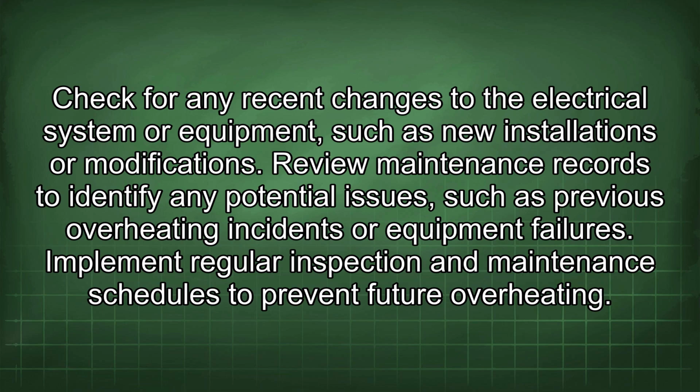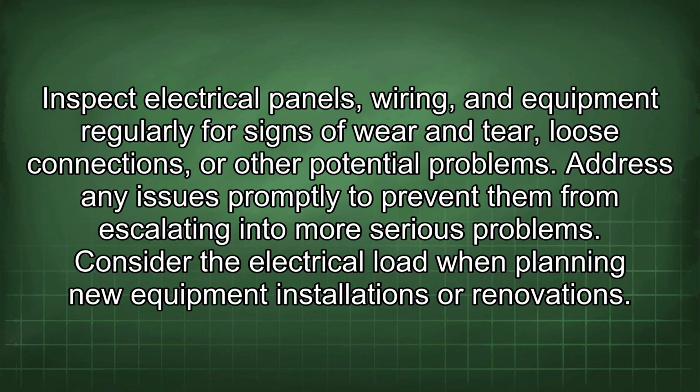Implement regular inspection and maintenance schedules to prevent future overheating. Inspect electrical panels, wiring, and equipment regularly for signs of wear and tear, loose connections, or other potential problems. Address any issues promptly to prevent them from escalating into more serious problems.